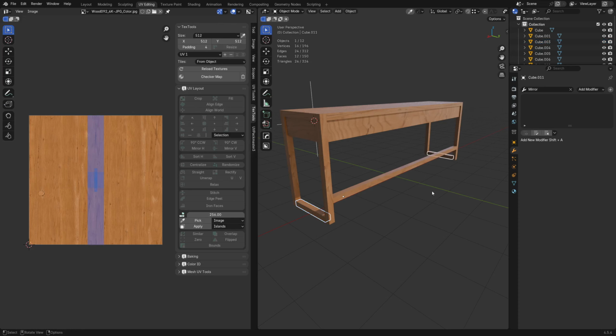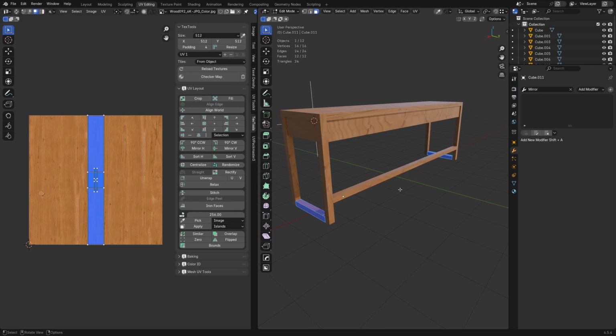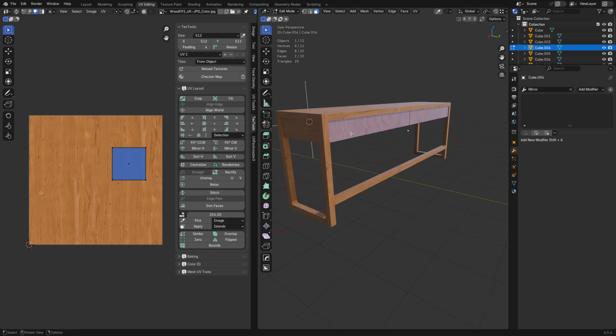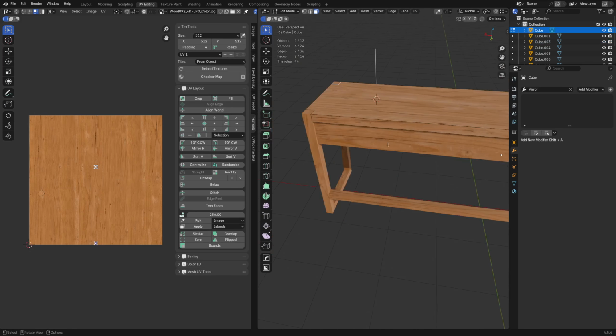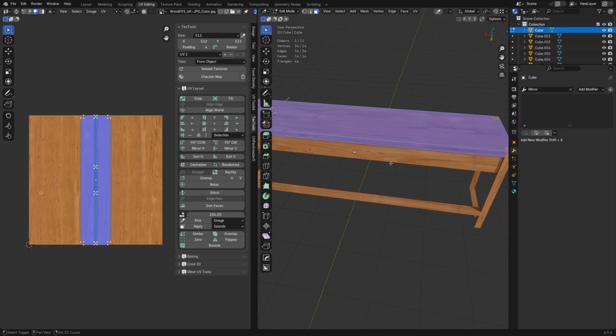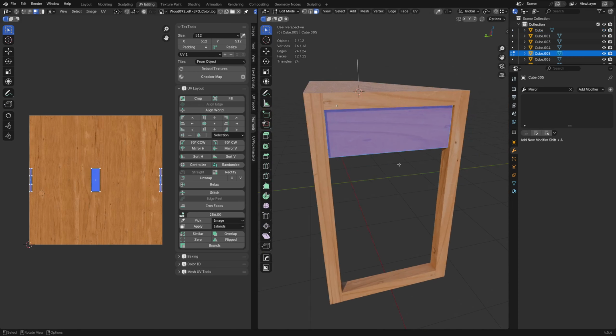We can just press Control J and join them back together. So you shift select them, Control J, go back into edit mode, U, cube project. This actually works pretty well for these pieces, although we might not have the right texel densities, so we'll get into that in a second. That actually works best with an add-on. So I'm going to Alt Q these, hit U, cube project, see if they come in okay, and if they all work out and line up and whatnot, right?